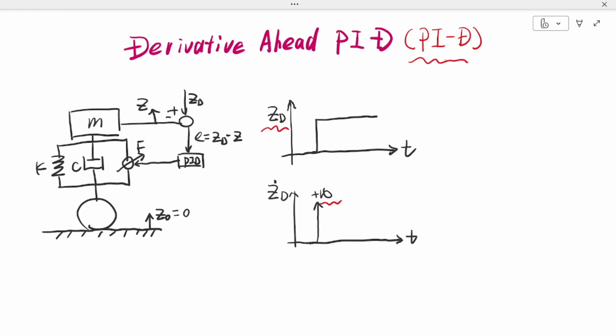We will build on the case study from our last episode. This time, we will set the road disturbance Z0 to 0, meaning the vehicle is right on a perfectly flat road. Now, imagine the vehicle is about to cross a flooded area, and we need active suspension to proactively raise the ride height by 5 centimeters. Therefore, our reference value curve ZD can be modeled as a step input with amplitude of 0.05 meters, triggering exactly at 1 second.